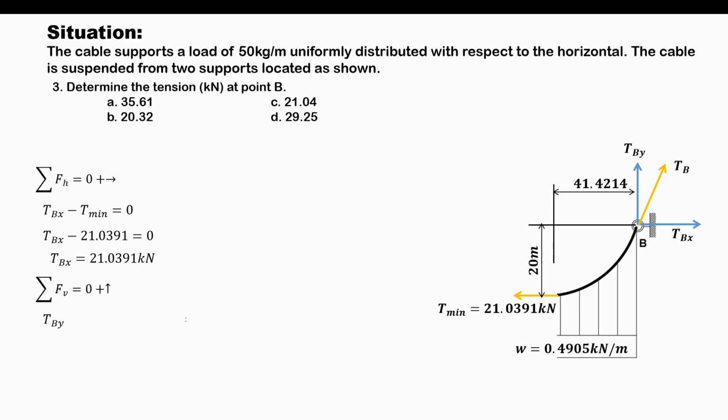So the other remaining vertical force that would be involved in this equation would be the resultant of the weight being carried by the segment being considered. So we've denoted the resultant of the weight here to be W2. And since this force is acting downward, we have here negative